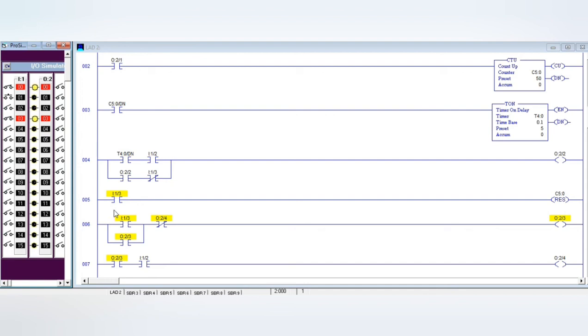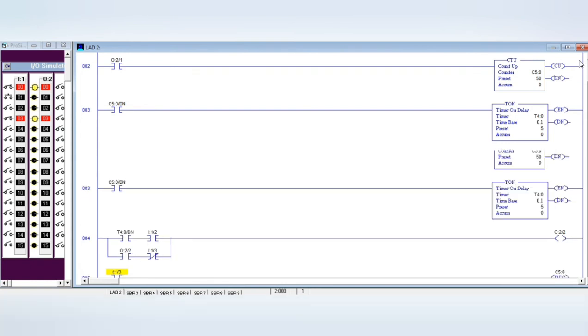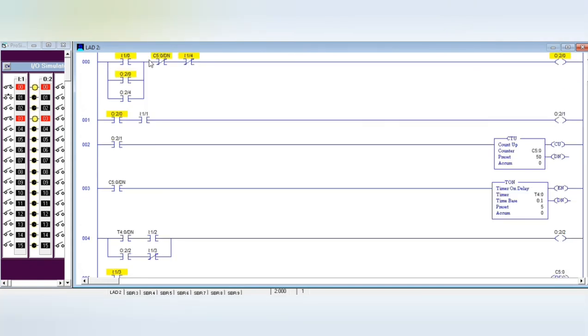Now you can see it goes back, which means it retracts, and then we have this reset function, which makes the accumulator and the timer go back to 0. Then we can start all over again. The entrance gate opens, the cans pass through the tube, the 50 cans have passed, and then the entrance gate closes again, the cylinder starts to move, crushes the cans, then moves backward again. And that's all for the PLC diagrams.